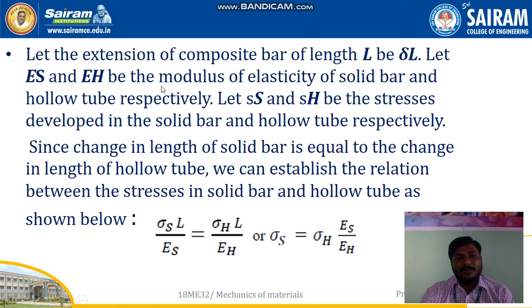Let ES and EH be the modulus of elasticity: ES is the modulus of elasticity of the solid bar, and EH is the modulus of elasticity of the hollow tube, respectively. Next, let SS and SH be the stresses developed in the solid bar and the hollow tube, respectively. Since the change in length of the solid bar is equal to the change in length of the hollow tube,